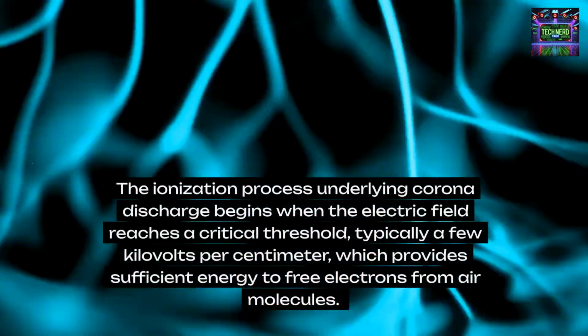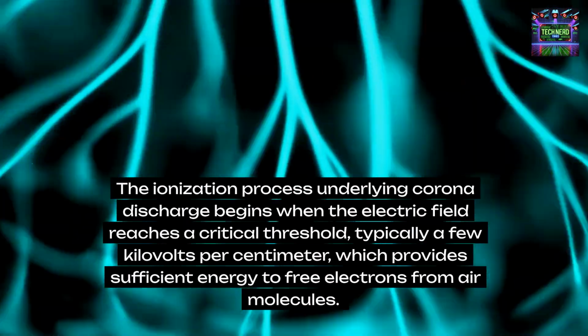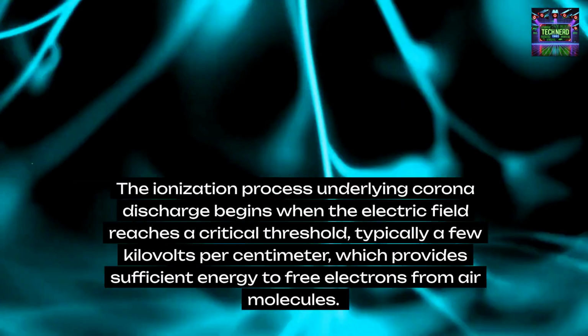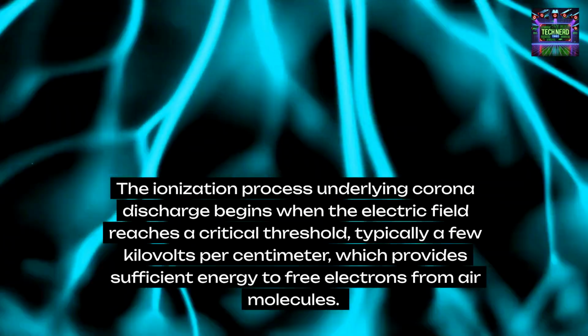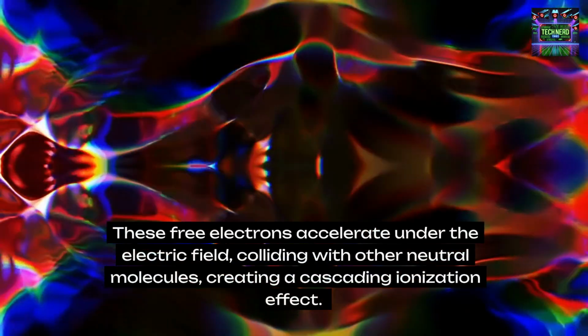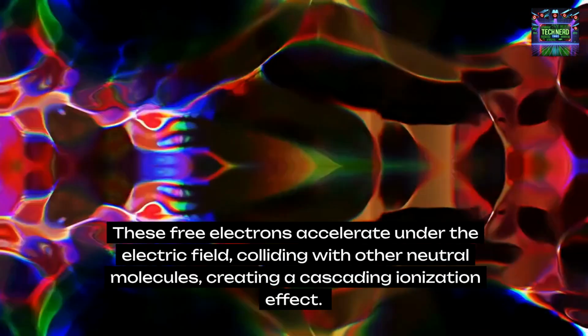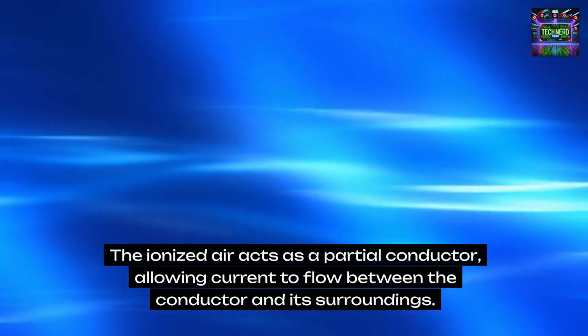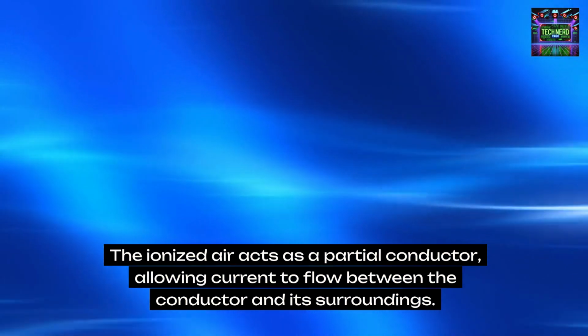The ionization process underlying corona discharge begins when the electric field reaches a critical threshold, typically a few kilovolts per centimeter, which provides sufficient energy to free electrons from air molecules. These free electrons accelerate under the electric field, colliding with other neutral molecules, creating a cascading ionization effect. The ionized air acts as a partial conductor, allowing current to flow between the conductor and its surroundings.